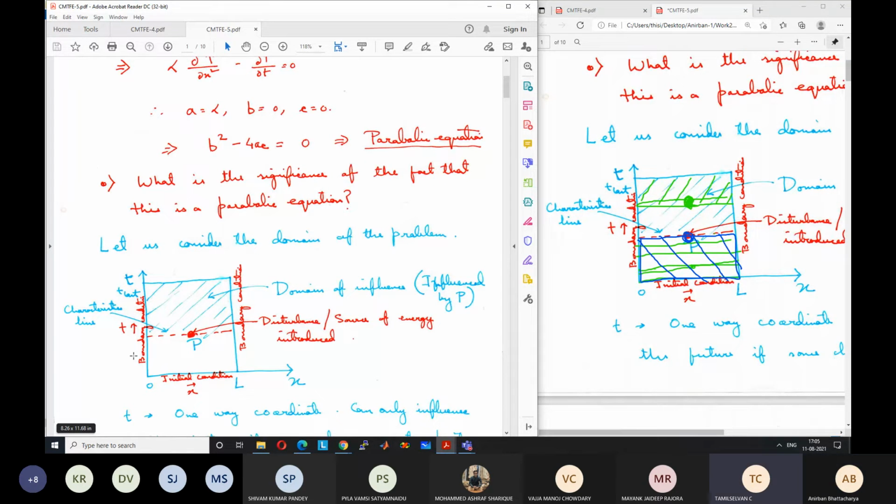Diffusion happens only along the flow. Diffusion should have happened in both directions, but here diffusion is negligible as compared to convection or advection. So the flow is carrying the ink. You are correct that the movement will be in only one direction, but the technical term is not diffusion; it is advection, or transport, occurring in only one direction, the direction of the flow. So it is as if the disturbance we have introduced can only influence the x direction in the tube, the direction downstream of that point.